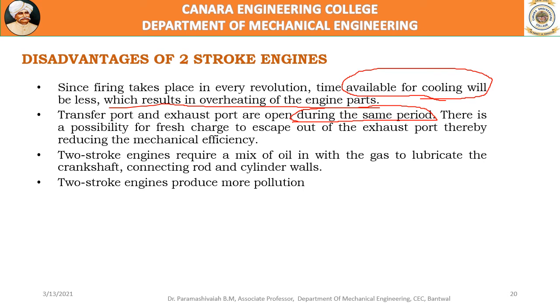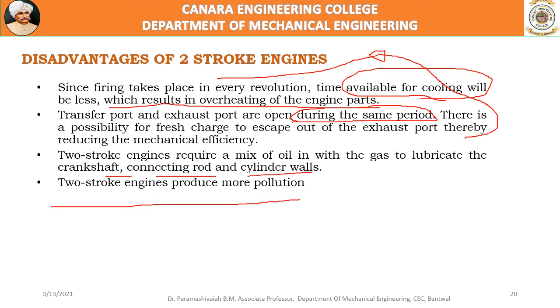Whatever the fresh charge, air fuel mixture, coming from the crankcase into the cylinder through the transfer port, some of that will escape through the exhaust port. So there will be some loss of fuel. So that leads to loss of efficiency of the engine. A two-stroke engine requires a mix of oil in the gas to lubricate the crankshaft, connecting rod, cylinder valves, etc. Two-stroke engines produce more pollution compared to four-stroke engines.